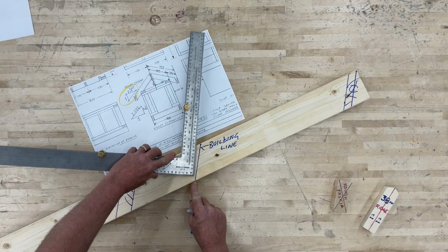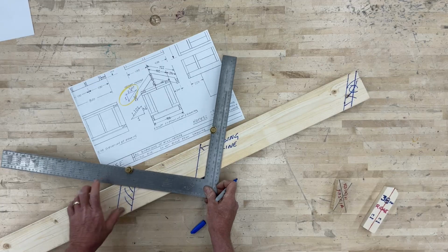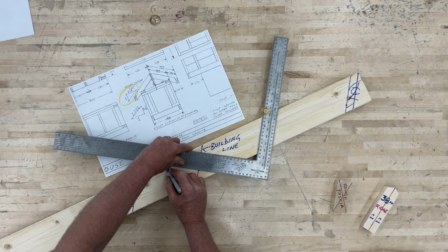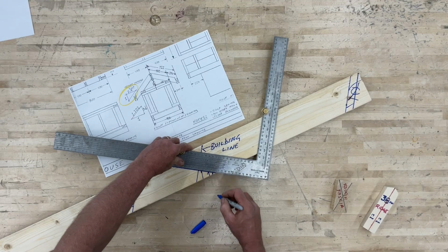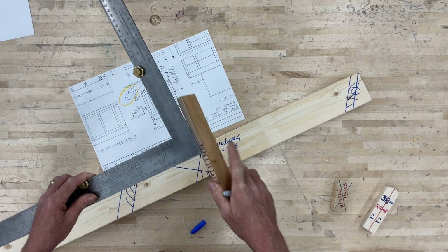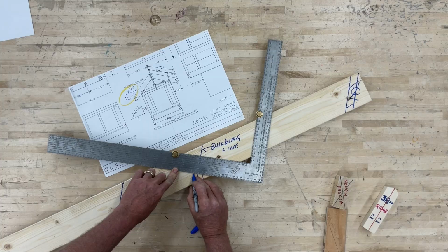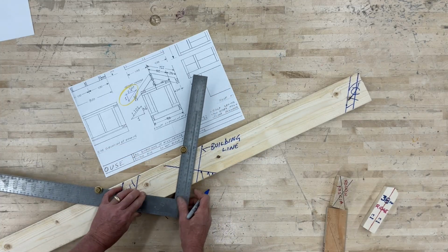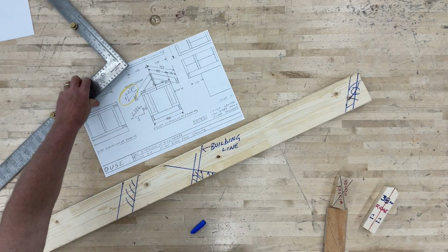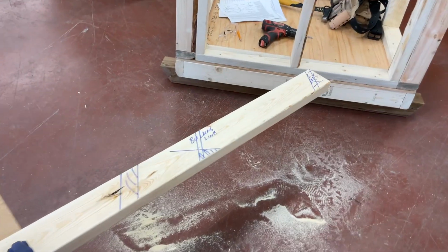For the seat cut, make sure that the bird's mouth ends up no more than 1/3 of the width of the rafter, and that the seat cut is no longer than the width of the top plate. Again, if sheathing is applied before the rafters are cut, extend the bird's mouth plumb cut to allow for the thickness of the sheathing. Mark your bird's mouth cut lines long to make them easier to follow with your circular saw. There's the rafter ready to cut out.